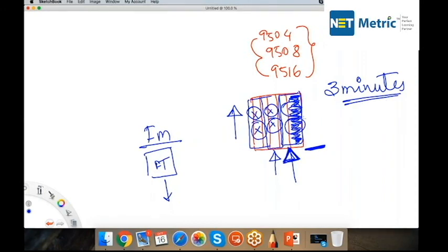Your device will start reloading every 3 minutes. So, whenever you want to remove multiple fan trays, please do not remove them at the same point of time. Remove one, get it serviced, fix it back, and then remove the other fan tray. Please do not remove two or more fan trays at the same point of time.